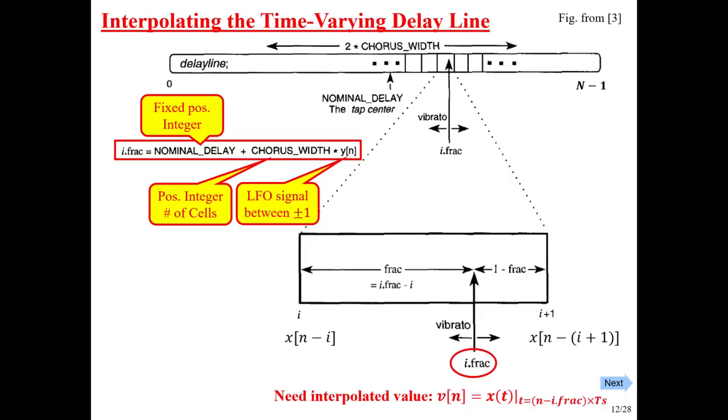So again, remember these lines represent the positions, the actual delay values of the samples that are stored here and here. So here is that line and here is that line. And so we're talking about delay. If this is going to be a delay of I, this one has a delay one more than that, so that's going to be a delay of I plus 1.